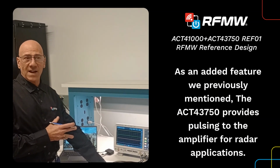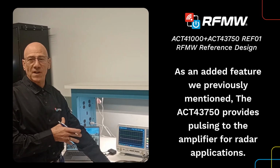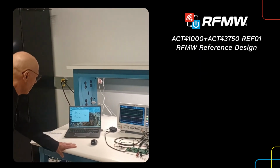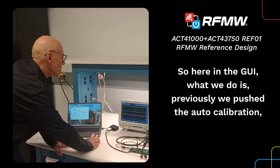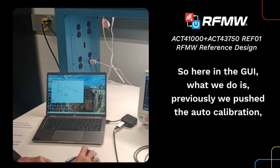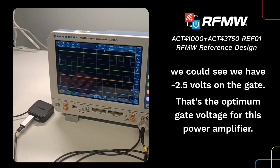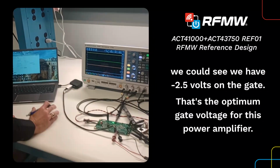As an added feature, we previously mentioned the ACT43750 provides pulsing to the amplifier for radar applications. I will now demonstrate that. So here in the GUI, previously we pushed the auto calibration. We could see we have 2.5 volts on the gate. That's the optimum gate voltage for this power amplifier.